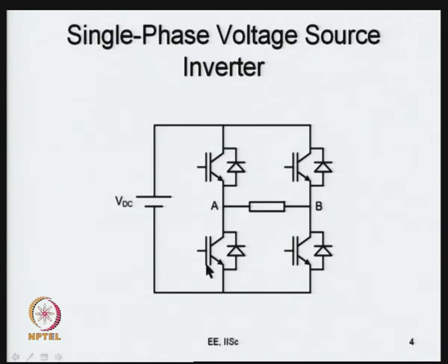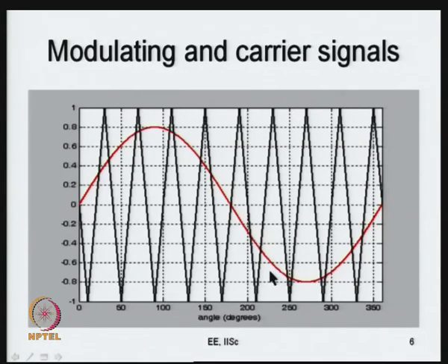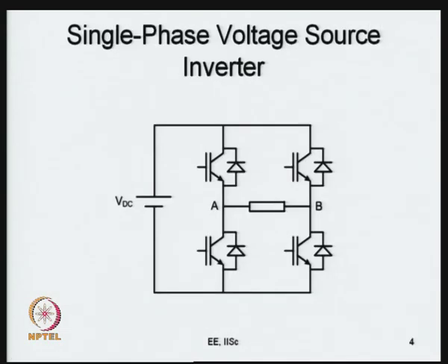So, that is the bipolar PWM, and we would use the more popular unipolar PWM. If you go to that unipolar PWM, first let us just look at one leg and one sine wave corresponding to a leg. So, why do we use a sine wave? The idea is that the average pole voltage, the voltage at this pole, we want it to be modulated in a sinusoidal fashion with respect to the DC bus midpoint.